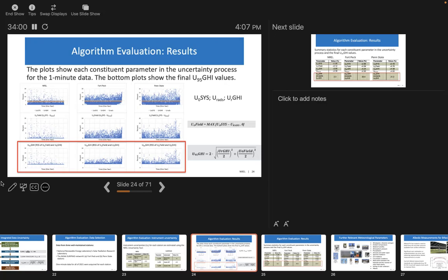And then there are these devices which have very fast response. These are photovoltaic, photoelectric, but their problem is they have a spectral response. The thermopiles are spectrally flat, so they can measure the whole range. You have to see from 300 to 4,000 nanometers. So that's why you use these instruments.